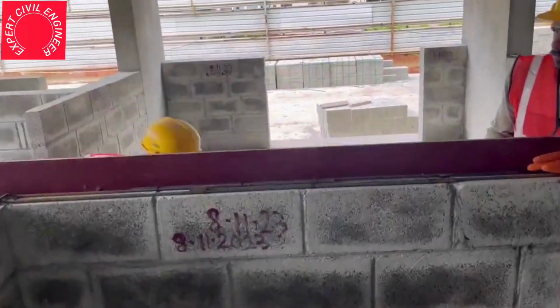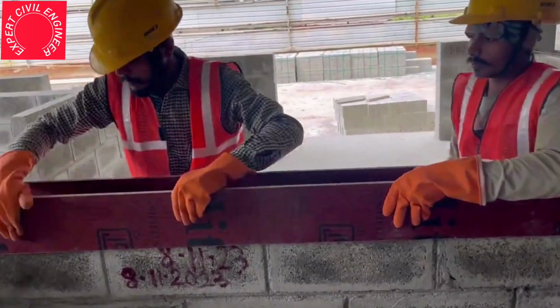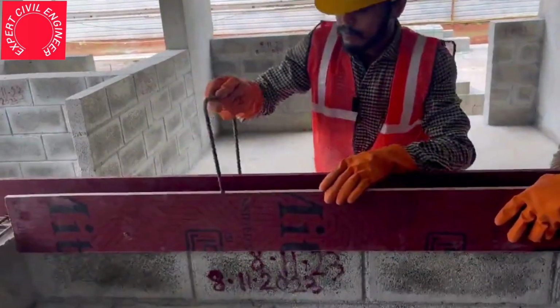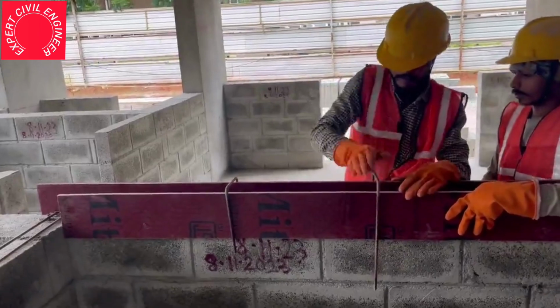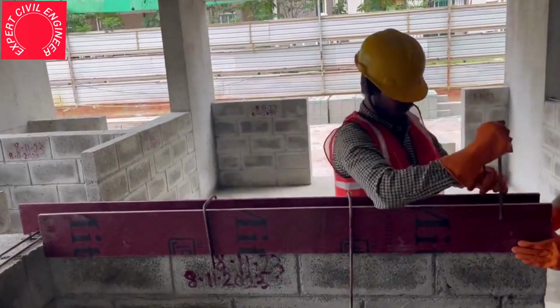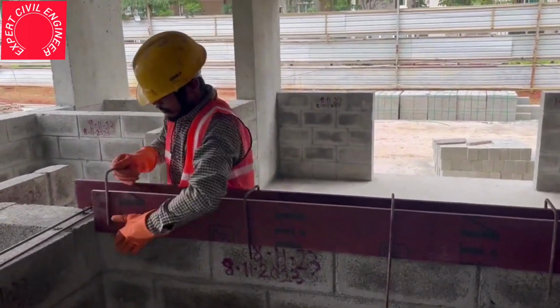Formwork needs to be carefully constructed for the sill level concreting process. As shown in the video, adequate support must be provided to the formwork to prevent bulging and offset issues that may arise after the concreting is completed. This ensures a smooth and uniform finish in the final element.